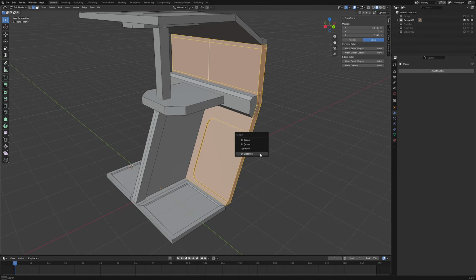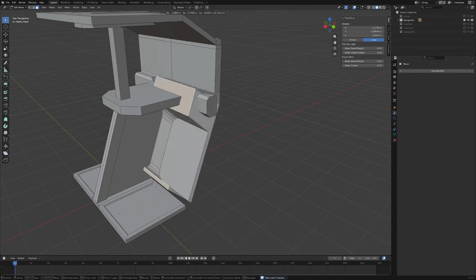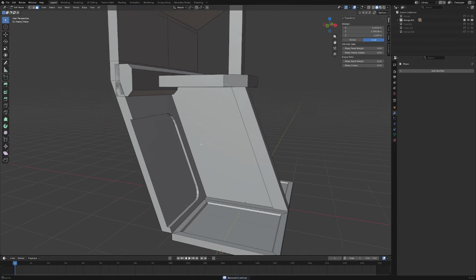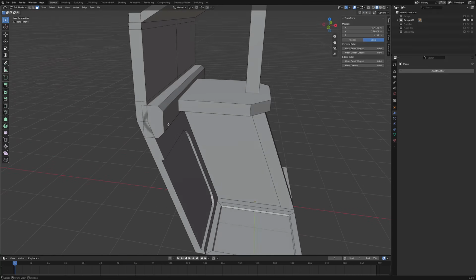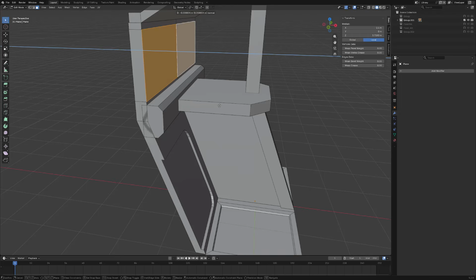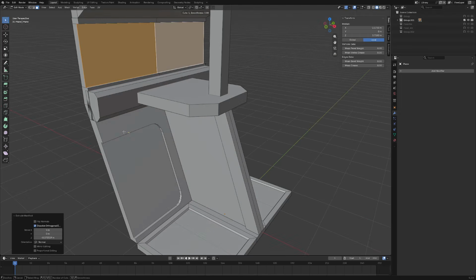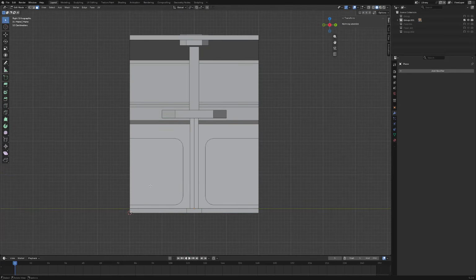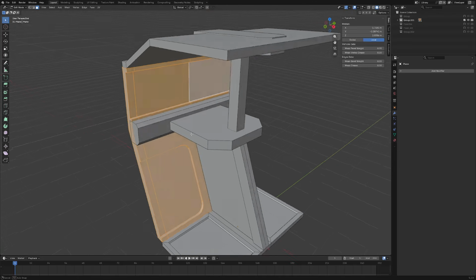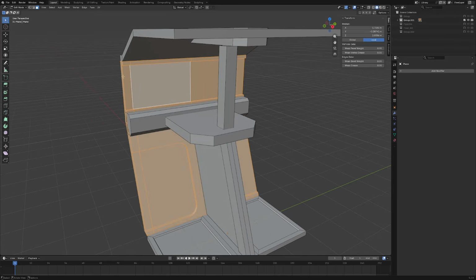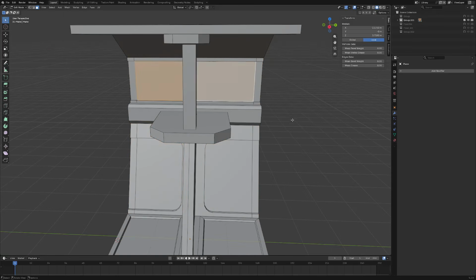I got doubles or something going on, or just some bad n-gons from that manifold extrusion maybe? That's probably what's going on. Sometimes that can happen. Like it shouldn't have done a loop cut through there anyways. It's a big n-gon. You should be able to do a K, C, A, cut all the way through if you wanted to. Okay. And that's all I was trying to do, to get this pushed in a little bit further so I could symmetrize like that.